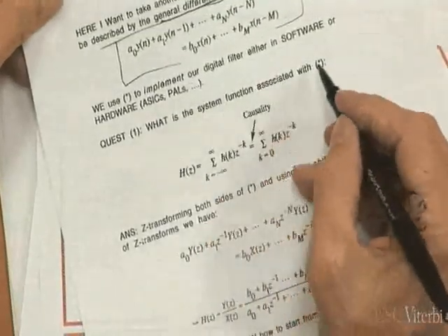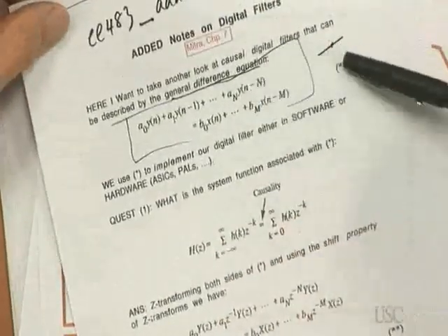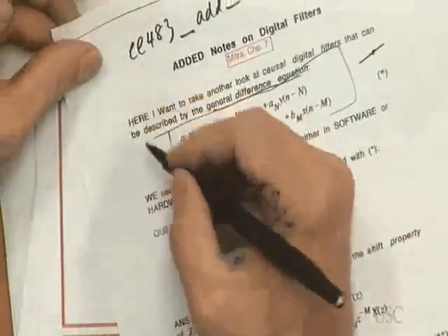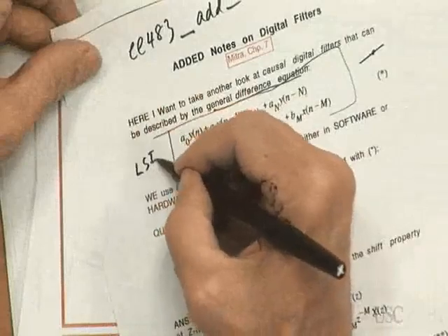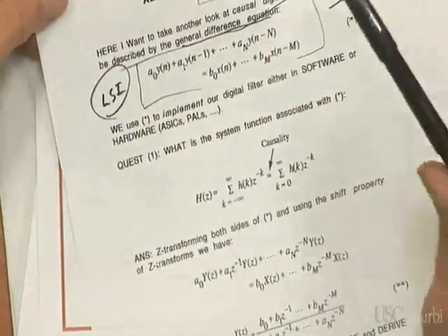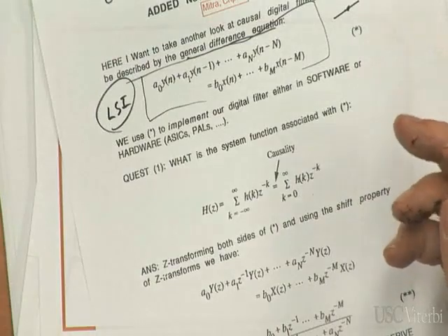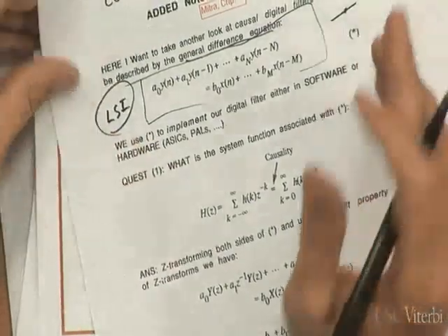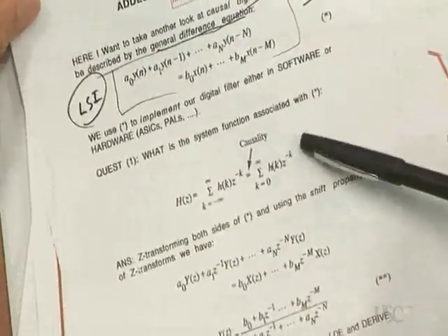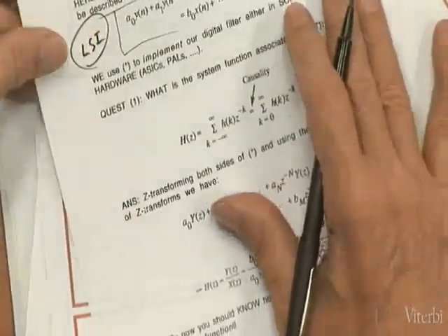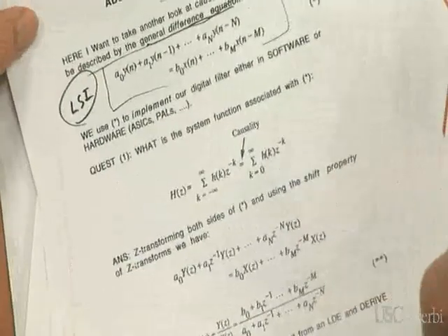So what is the system function associated with this? Yeah, and again, this is causal. This defines a linear shift-invariant system. It has all the right initial conditions, etc. So my first question is, what is its system function? Actually, your first question is, what the hell is the system function? Can you tell me what that is again? The system function is the Z transform of the impulse response. Okay, now how in the world do you get that? Well, you get it several ways.